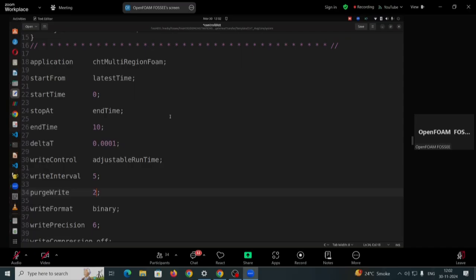If you want to see how your system responds to a transient change, you will have to do a transient simulation. But for a case like the one we are solving, even a steady state simulation is possible. We have shown you transient, but it can be switched to steady state because you are only interested in what the temperature will be once it reaches steady state. In that case, always go for steady state, it will converge faster.